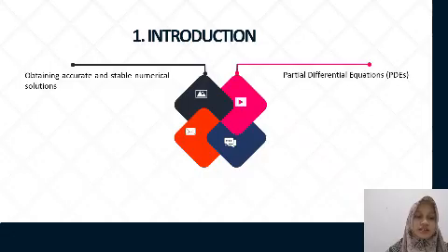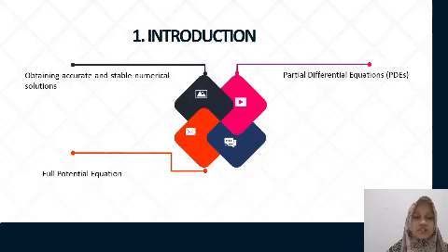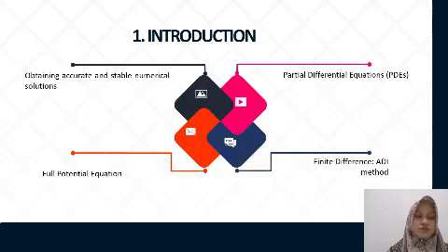The nonlinear full potential, widely used for inviscid and irrotational flow, requires efficient numerical methods, and the alternating direction implicit or ADI methods offer an effective solution by splitting a problem into alternating one-dimensional steps. This approach enhances stability, accuracy, and computational efficiency, making ADI a strong framework for solving the full potential equations.